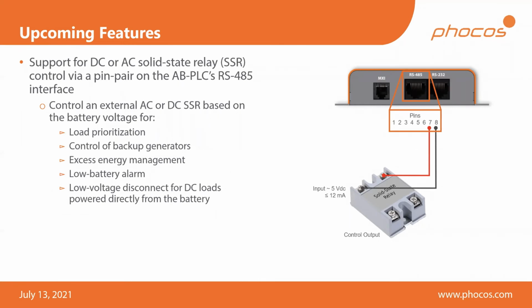This 5th feature is support for a solid-state relay. Essentially, I'm sure that most of you know what a relay is. It's essentially a coil, a switch, an automatic switch. A solid state relay is the same thing, except it's solid state. So it doesn't have any electromechanical components. It is a purely electrical device with no mechanics in it. In other words, it is a semiconductor. Now, these come in two flavors. There's solid state relays, which are abbreviated here as SSR, in AC or DC variants.